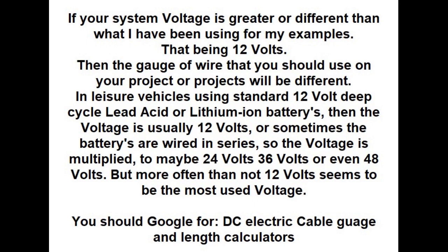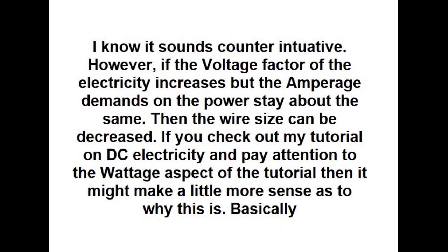In addendum, different voltages should also be taken into account. It's not always going to be 12 volts. It could be 24 volts. It could be 48 volts. In this case, you should look up the wiring on charts on Google, DC wiring charts. There are also calculators out there that can be Googled on the internet that will aid and assist in getting the correct wiring gauge for these higher voltages. And technically, as the voltage gets higher, you can use a thinner wire. So if you're using 24 volts, you're going to use a slimmer gauge, a thinner gauge than if you were using 12 volts. And 48 volts will again use an even thinner gauge wire than, let's say, 12 volts.